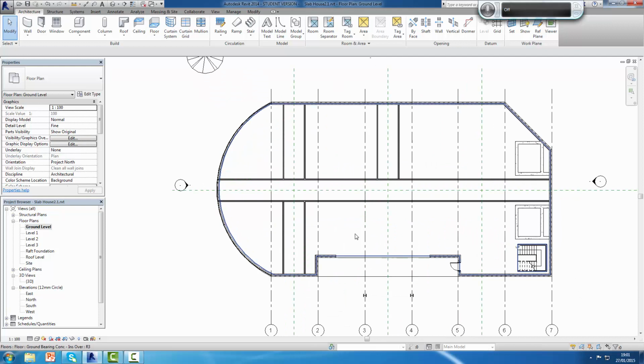So within that area now, we're just using that offset command and the reference plane. We've got 3 corridors in there. It may not be the greatest of plans, but we'll see as we go further along. We can delete the walls out, we can add another wall, we can cut a wall away, make those small offices. We can do in a sense what we wish with the ground floor.